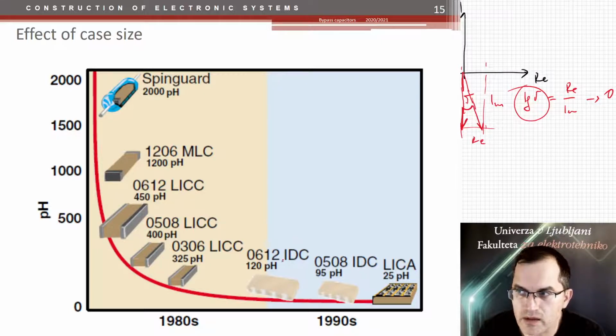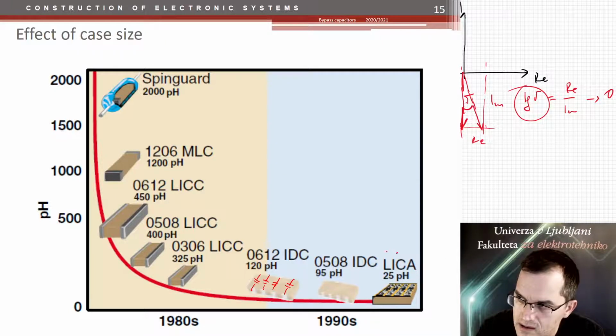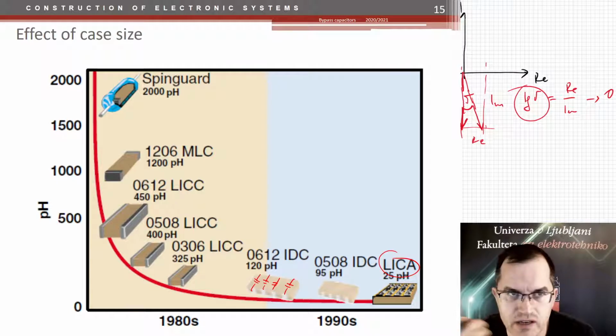Then you have interdigitated capacitors, which are more or less more capacitors in parallel, like that. And this would even decrease the series inductance. And there is a reverse geometry form, which has the lowest inductance possible. It's in a BGA format.